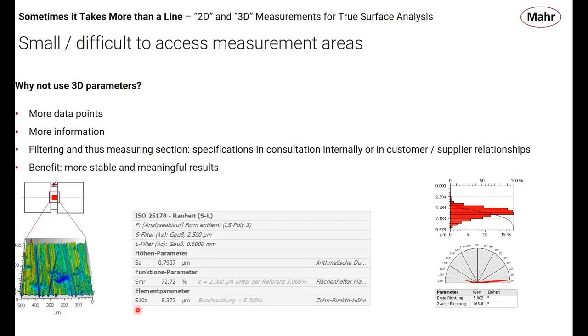We have 2 orders of magnitude more information than that from a single measurement. And my proposal to you is that that is going to give you a much more reliable representation of what's happening in that groove than a 2D measurement. And here we're showing a typical 3D measurement that we would use, producing the Sa value, which is the 3D equivalent of the Ra measurement.